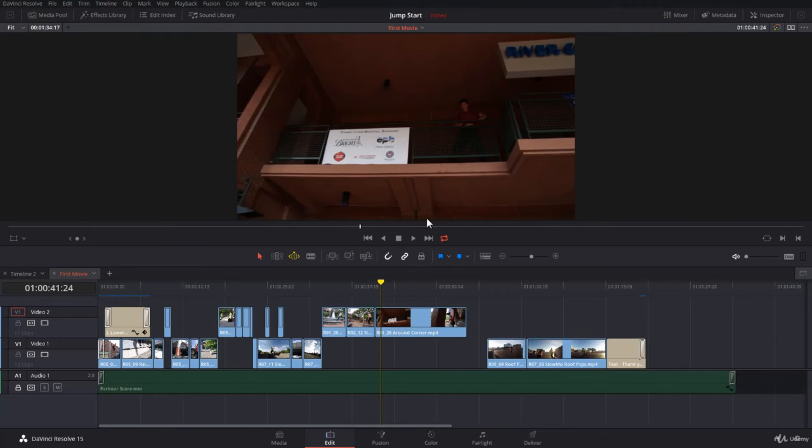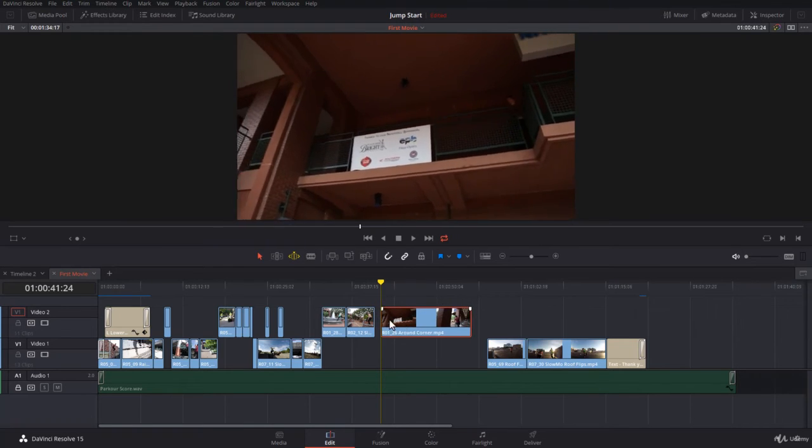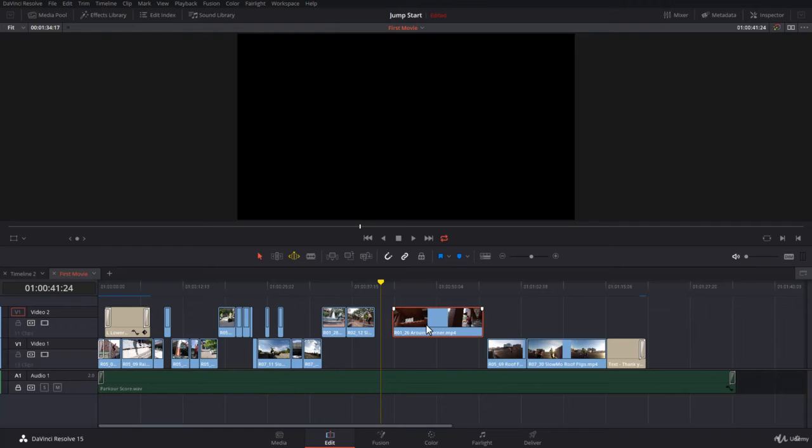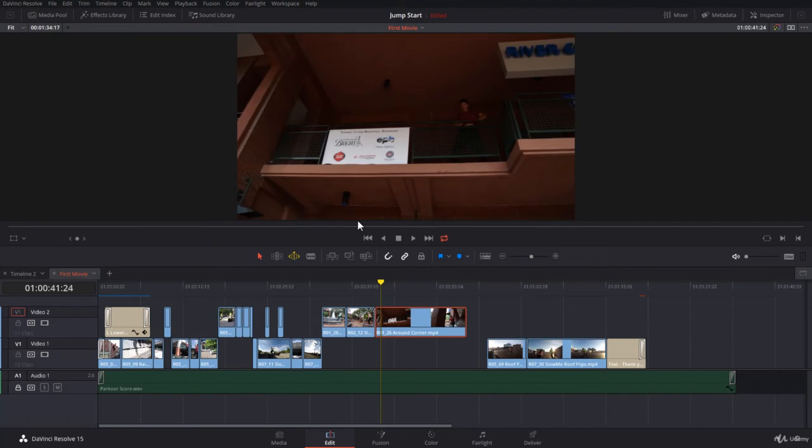Now I'm going to deselect and select the clip itself. Now, if you are in the slide mode or in the sleep mode here, it won't make a difference because you are in the selection mode. Now, immediately I start using the L. Notice you're doing now an automatic slide. Now be very careful how you press on the L. If you press it more, you notice it's going to speed up. If you press too much, it's going to fly over. If you go to get a cup of coffee, you will find it after 4 hours at the end of the timeline. So I'm going to undo this.